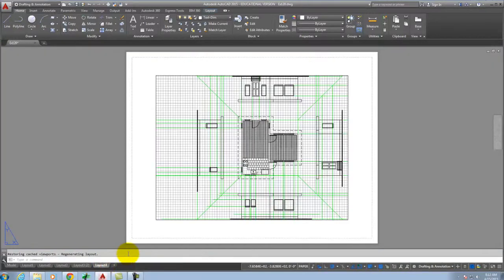And when you do that, the screen changes to be white. Right? And then you have kind of a box that's inside your screen that has your drawings in it. Okay? This is called Paperspace, where the black is called Model Space. The main idea behind Paperspace is this is a sheet of paper as if I were going to go print. Okay? And my drawing shows up on this sheet of paper, right? And when I go to print it, it's going to come out what it looks like.